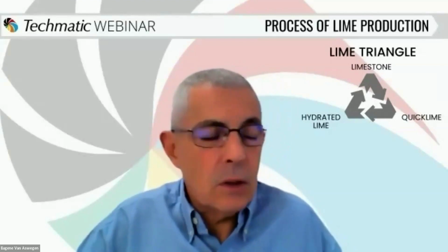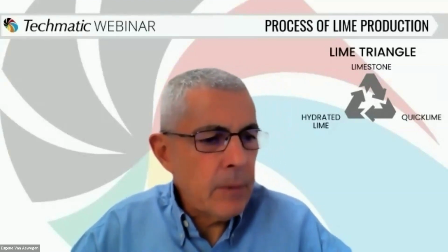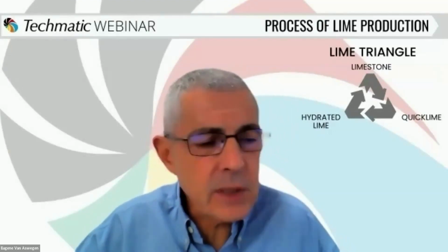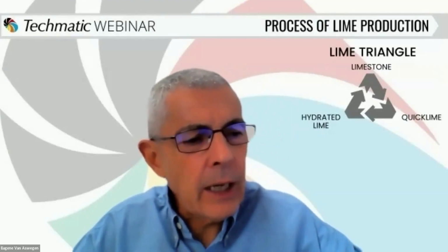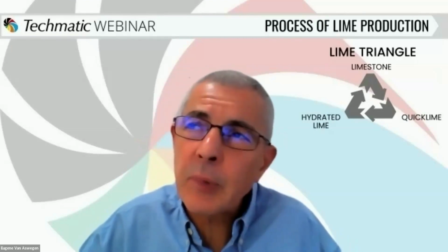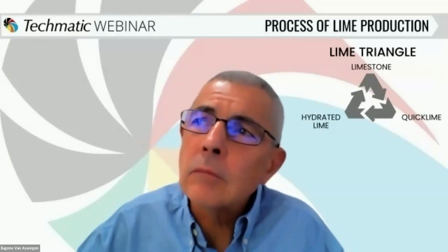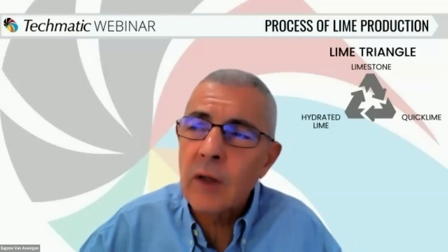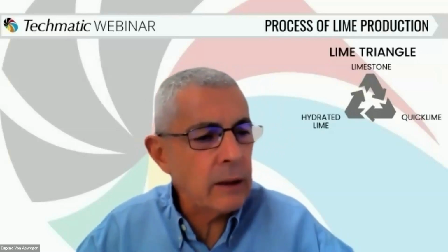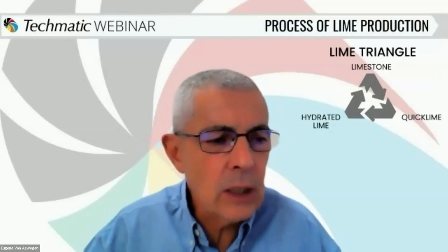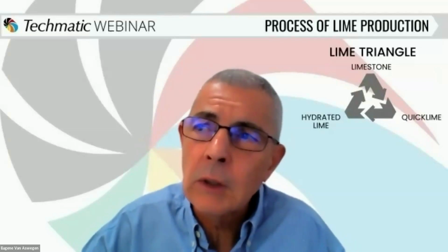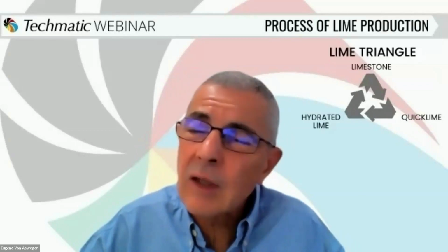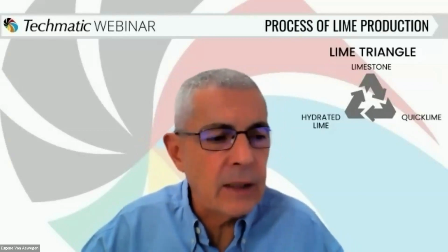Karsten, yes, thank you, and thanks, Prince, for the question. I'd like to clarify one point in case I may have misled our listeners. Correctly, as stated by Prince, available calcium in limestone is about 95 to 98%. What is important to note, and I didn't state it, so my apologies, is that once you've burned the limestone, the available calcium drops to anything from 85 to 89%.